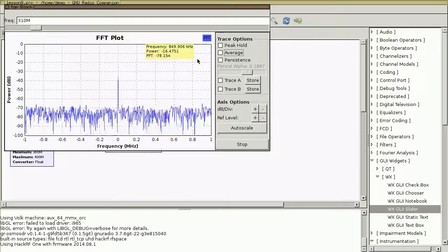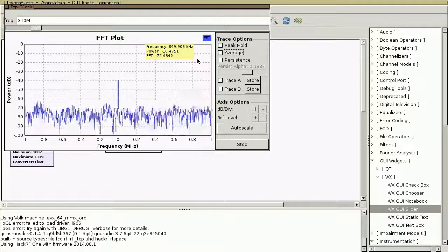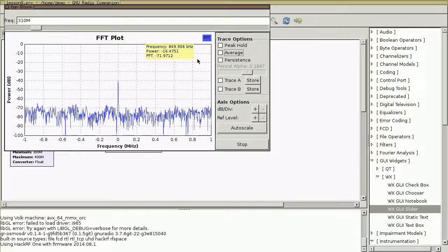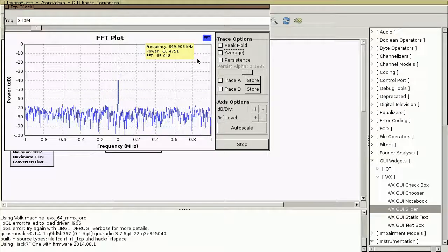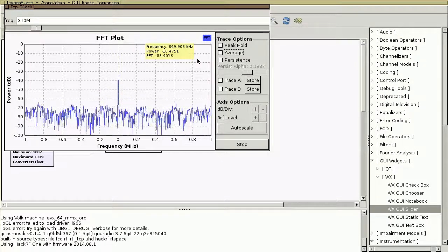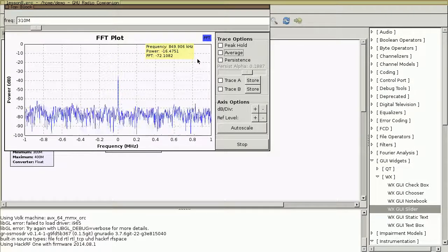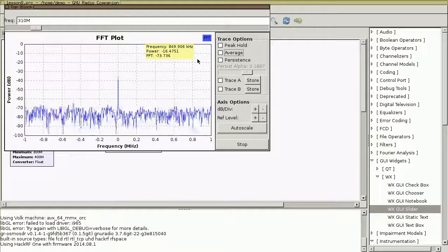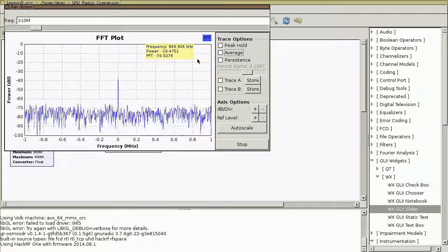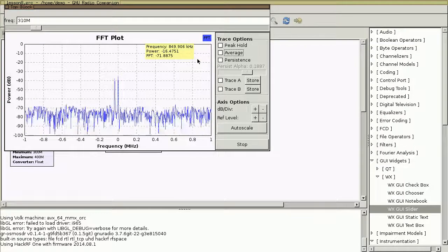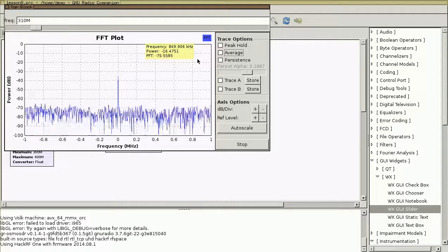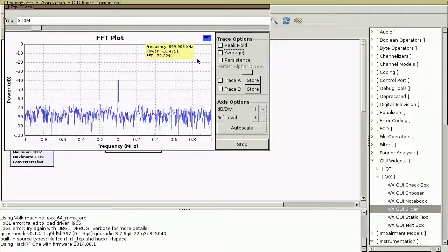If I hold it right next to the antenna of the receiver, you can see we're actually getting some other frequency components because we're distorting a little bit, because we're up pretty close to 0 dB. But if I hold it at a more reasonable distance, like a meter away, then I'm at somewhere around -30, -40 dB, and we seem to get a nice clean signal for as long as I hold down the button.